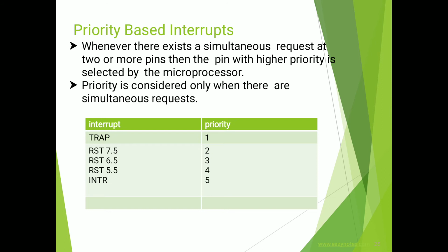Priority is given below. The trap has the highest priority, then RST 7.5, then RST 6.5, RST 5.5, and finally INTR is the lowest priority.